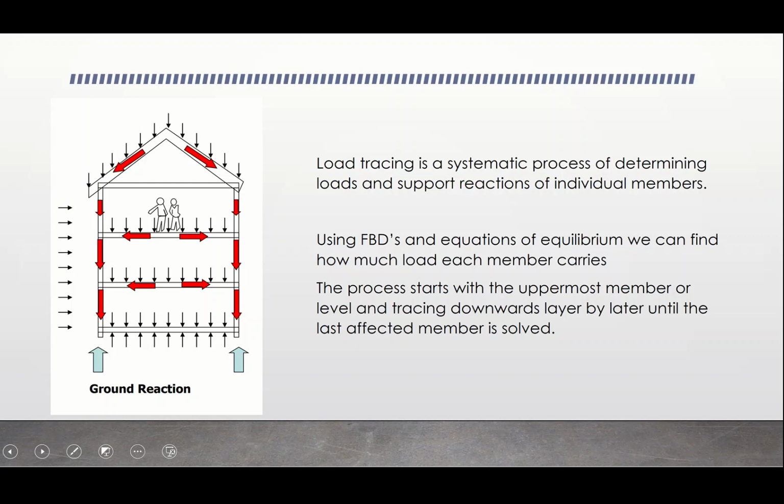Okay, when we talk about load tracing, we're starting from the top and working our way down always. So load tracing is a systematic process of determining the loads and support reactions of individual members. So we will go from just the base, just the decking, planks, whatever the case may be, to the beams, to the joists, to the girders, to the columns, to the soil. Okay, that's kind of how we'll be going in this class.